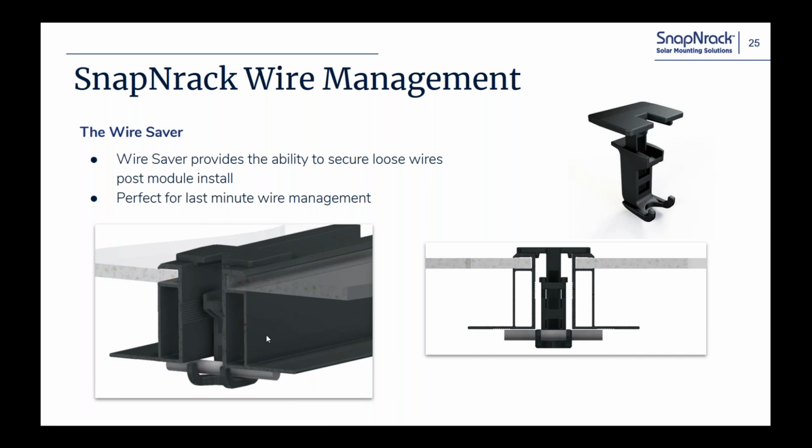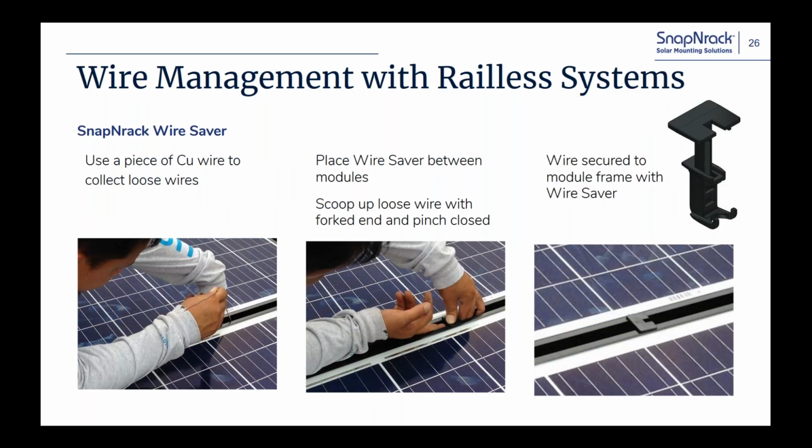Which over cycles of wind, snow, whatever, dragging that PV wire back and forth across the composition, you're going to pull the shielding right off it pretty quick. So you definitely want to make sure all this stuff is tight up against the module and inside the module frames. So here's an example of that kind of operation.